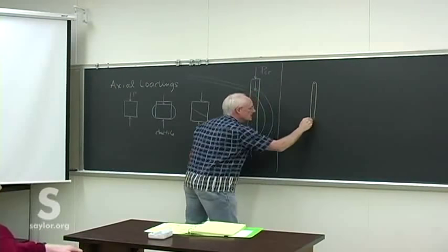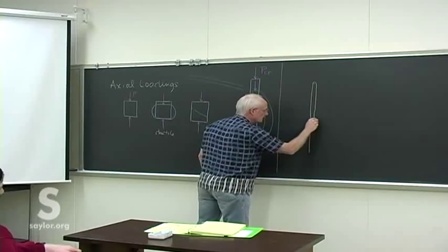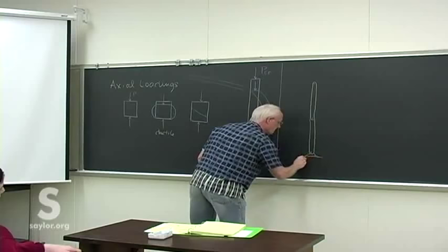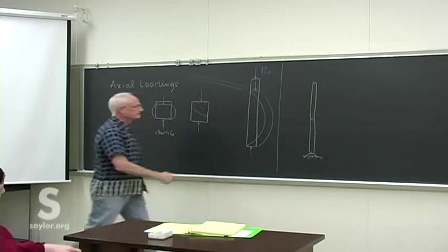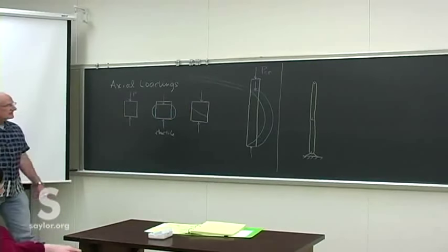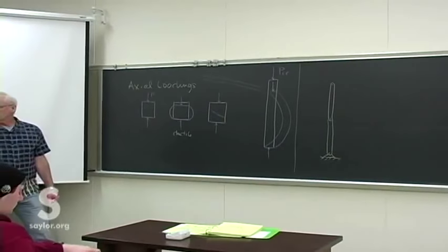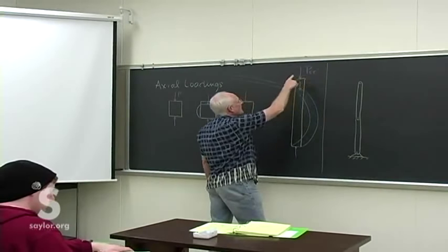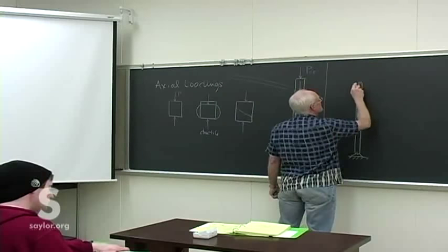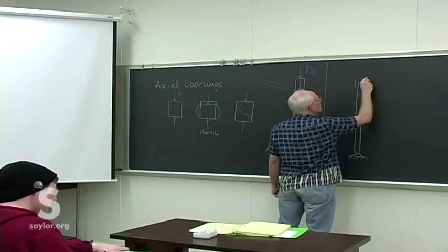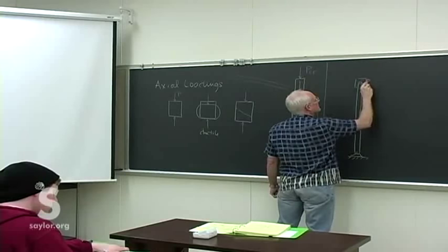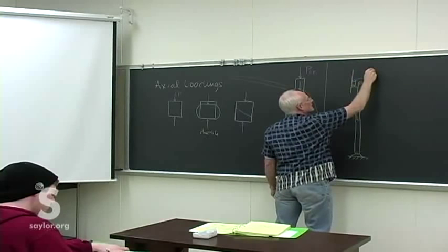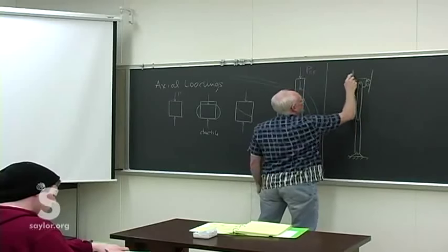So we're going to model this column to start with as a simply pinned two-member linkage. So it's two pieces of equal length pinned together. We need to allow the top to move up and down, so we can imagine that something like that will suffice.